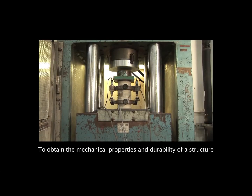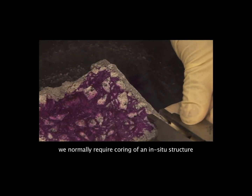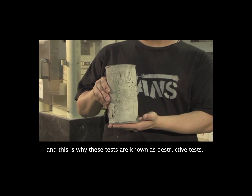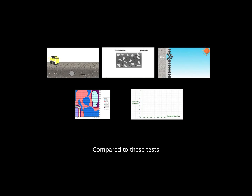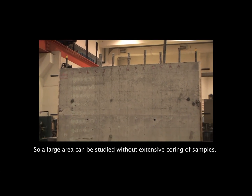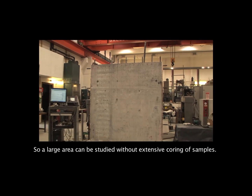To obtain the mechanical properties and durability of a structure, we normally require coring of an in situ structure. And this is why these tests are known as destructive tests. Compared to these tests, NDE tests do not disturb the concrete structure or only do so minimally. So a large area can be studied without extensive coring of samples.